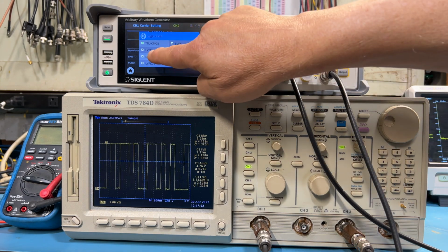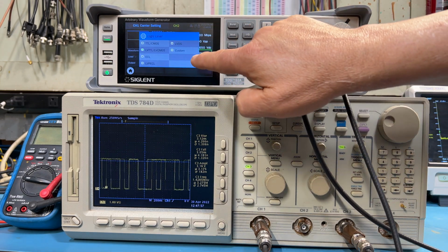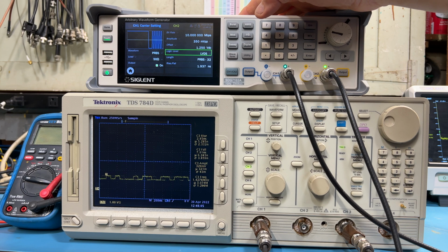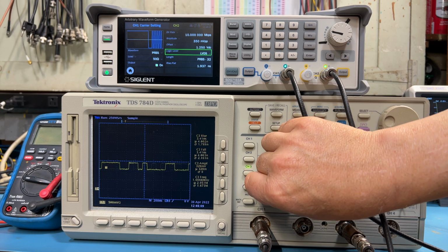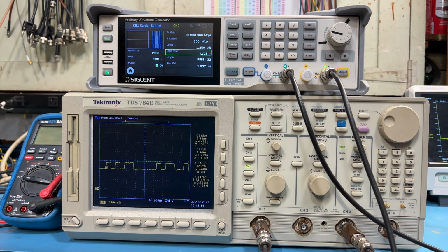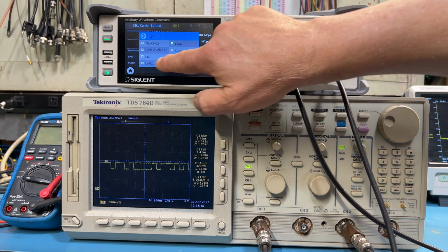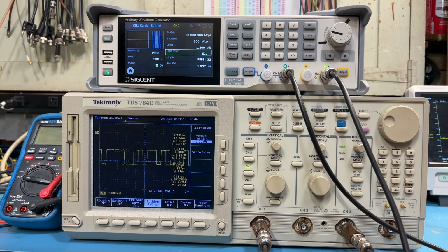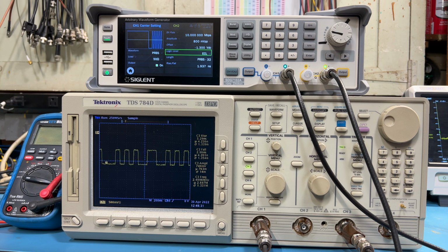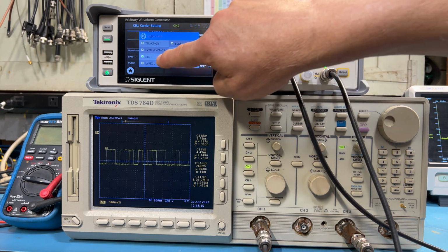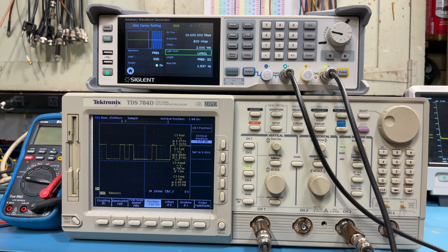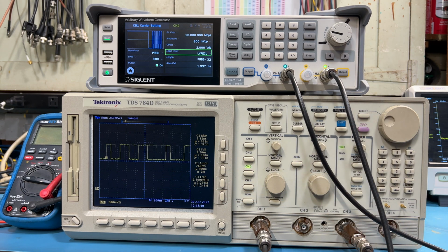Let's try low voltage TTL. It drops it down. Low voltage differential signal. Okay, so that's above ground. Emitter coupled logic, that's below ground, so let's go here. Go to 3. Okay. Low voltage positive emitter coupled logic. Okay, so now I've switched the ground level down to there. So these are kind of useful built-in levels.